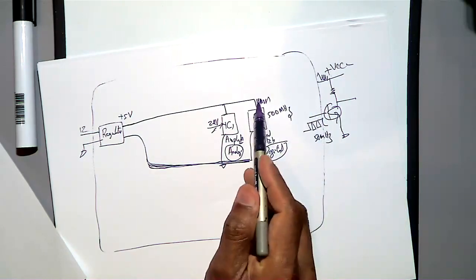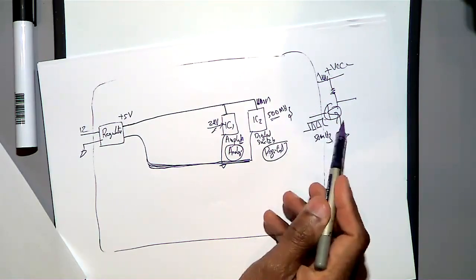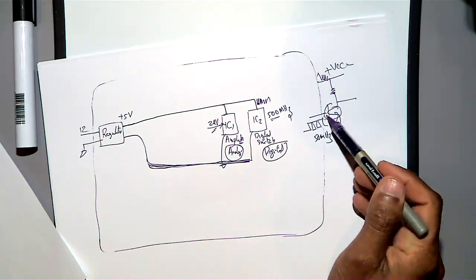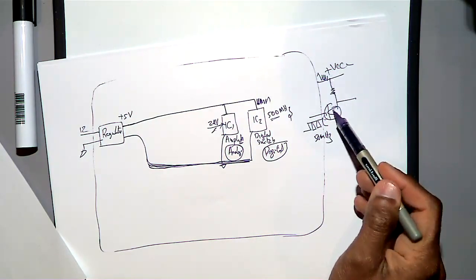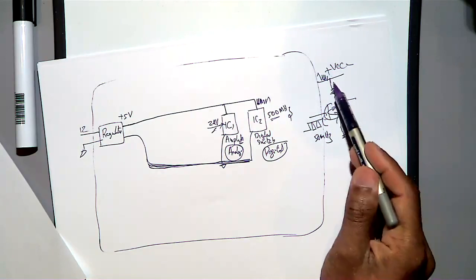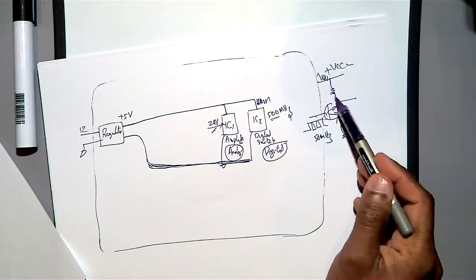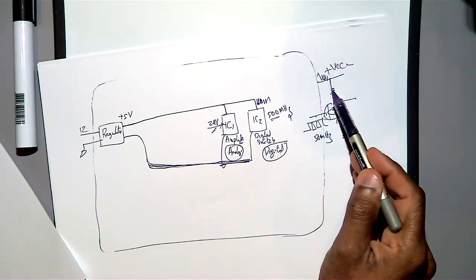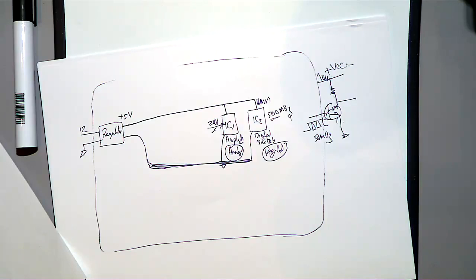And then that switching noise is due to switching the transistor on and off. When the transistor is on, power is drawn and collector current is flowing. When the transistor is off, the collector current is not flowing. You know what I mean? So at very high frequencies, you are drawing current and not drawing current depending upon the switching, and that will generate a lot of noise.